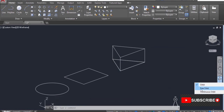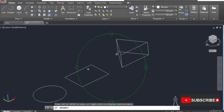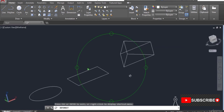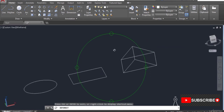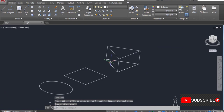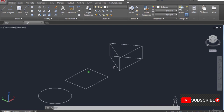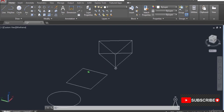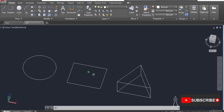We also have another orbit option, which is free orbit, that is useful for viewing our drawing more freely in different axes, and you learn about these tools in a much better way in our 3D course. So let's press the escape key, and now if you want to access the same tool using the mouse, you can do that as well. Simply press and hold the shift key, then press the mouse wheel, and instead of pan, that will convert it into this orbit tool, and now you can orbit the drawing in free space.